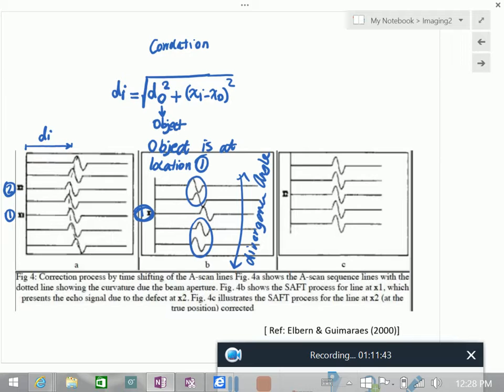So basically, you go ray by ray. You look at the neighboring rays, depending on the divergence angle that you know from your transducer. We just learned this. And then you correlate. You can think about it as this: if you sum everything up, they cancel each other. But here, everything adds up. So here, we know that, yes, the object is there. This is basically how it works.